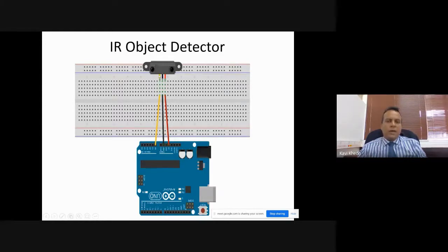Here is a reading of whatever is being captured by this sensor. Here it will be read and connected to this point here. If we go down on this side, I'm connecting a jumper wire. Actually, you could have connected any of those dots here, here, or on this one, because all these are connected on the breadboard on this side. So this is connected here, and this one I'm connecting to A0. A0 is an analog input, an analog port of the microcontroller.